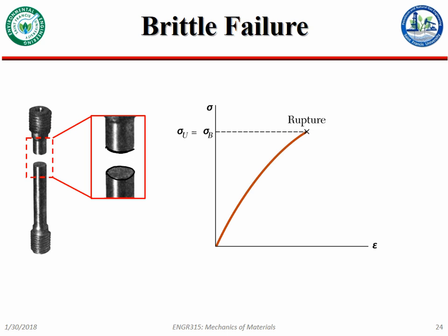Like you could piece together the glass and it would look like the actual piece of glass because it hasn't really deformed all that much. There's no or virtually no necking or other kinds of deformation at the break. It's as if the two bits just kind of snapped off from one another. That's a brittle failure. Now, it would be difficult to call any given material brittle or ductile. Well, it can be.